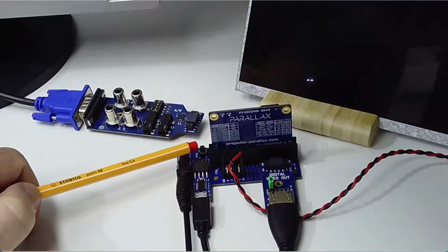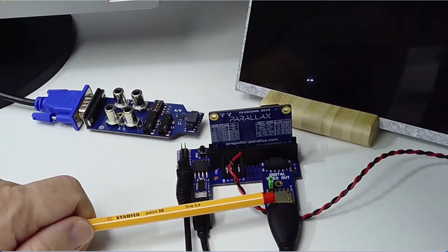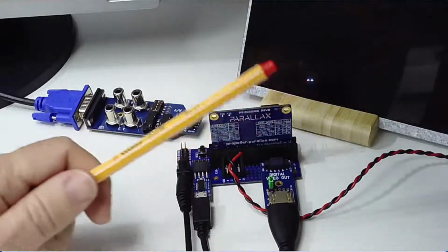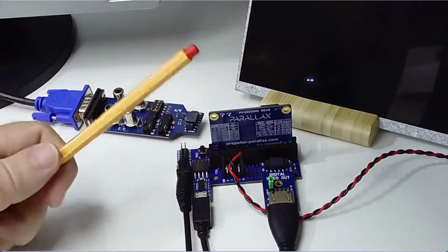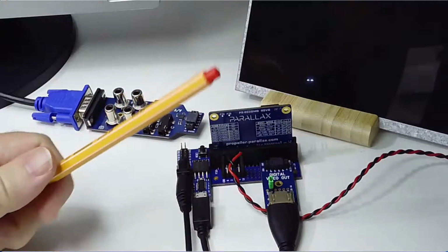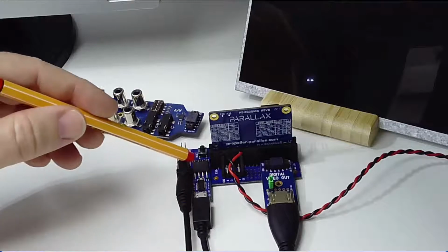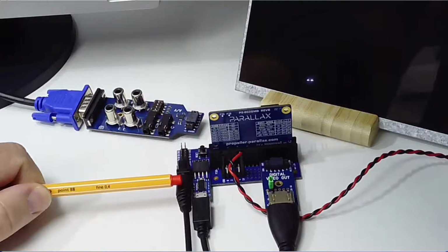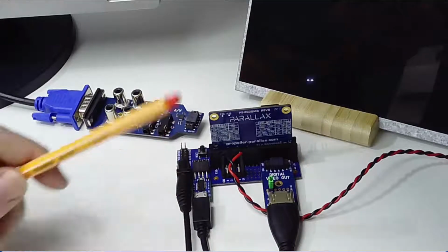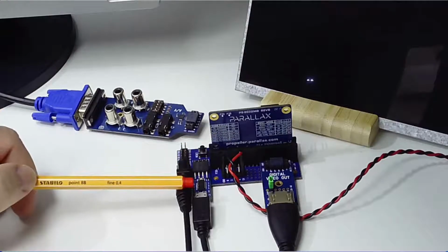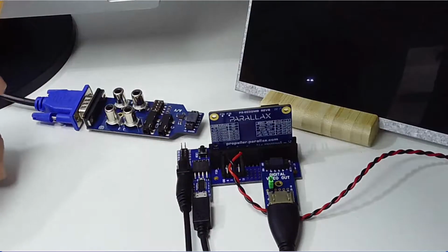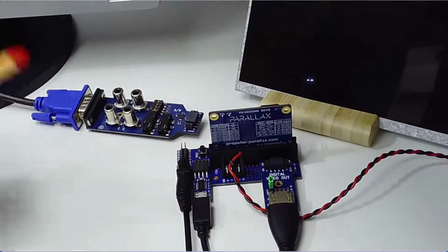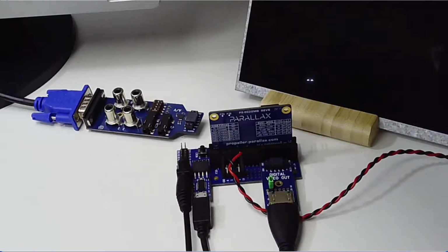And then I'm just running it through a mini breakout board with the digital video out accessory to provide us with the HDMI cable. I've got the HDMI plugged into this small 7-inch screen here, but you could use a TV or monitor as well. And then the usual things just for programming and powering. Power is coming through a 5-volt USB barrel jack from a USB 1 amp charger because I'm powering the screen as well from the same supply, so needed a bit more juice. And that's all, not using the VGA here, although you could plug in the VGA and use the VGA monitor instead as well if you wish.